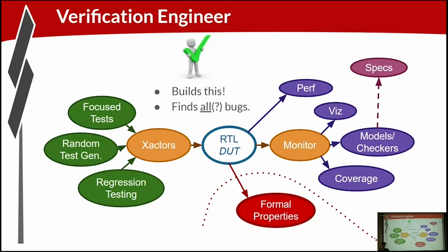In the case of the CPU, that's pretty simple. That's basically an assembler. You get the code into the model, into the instruction memory. For most designs, there's a little bit more intelligence around taking that stimulus in some higher level description and actually driving the physical pins of the design under test, the DUT, which would be your RTL model.